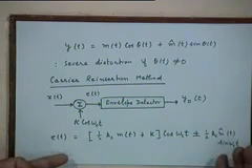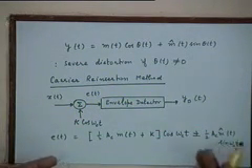This is in conformity with our discussion on the general representation of bandpass signals, which has an in-phase part and a quadrature phase part. Only thing is that there is a special relationship between the in-phase and quadrature phase parts for it to become an SSB signal, right? That we have understood now.